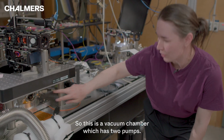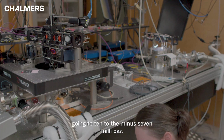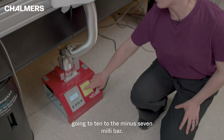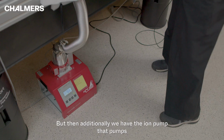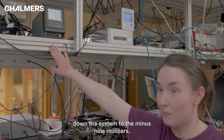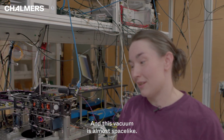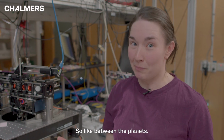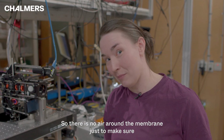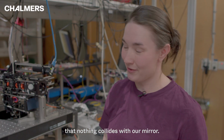So this is a vacuum chamber, which has two pumps. One will be the turbo pump going to 10 to the minus 7 millibar. But then additionally, we have the ion pump that pumps down the system to the minus 9 millibar. And this vacuum is almost as the space-like, so like between the planets. So there is no air around the membrane, just to make sure that nothing collides with our mirror.